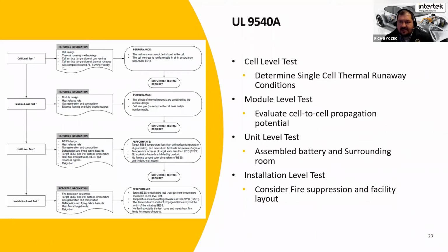The cell level test tells us how we can trigger a single cell event. The module level test allows us a small enough system that generally in a lab environment, we can get a lot of good data from this. Even if it did go into a full runaway, you have the ability to somewhat contain this within the laboratory.